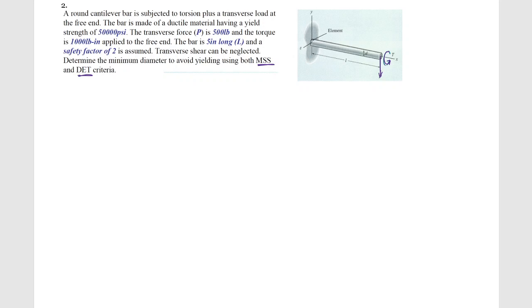Okay, so it's pointed out, not in the problem statement, but it's here, this element is the highest stress that I'm going to get. So at that point, I'm going to have maximum normal stress in tension from the bending. That bending is due to the My over I, which I know for a rod is always 32 M over pi d cubed. We've done that 1,000 times, and in this case, the moment is just the force times the length.